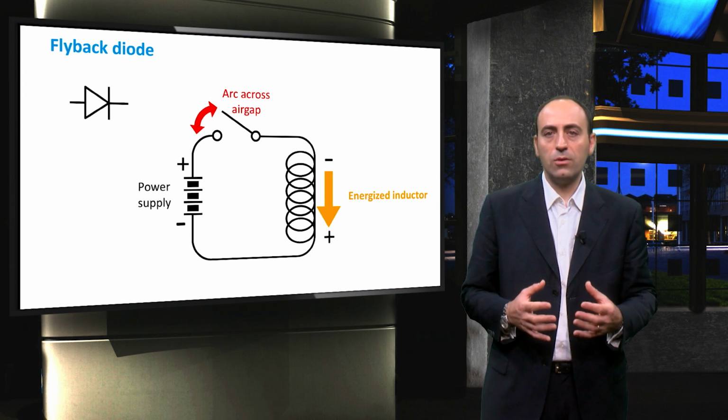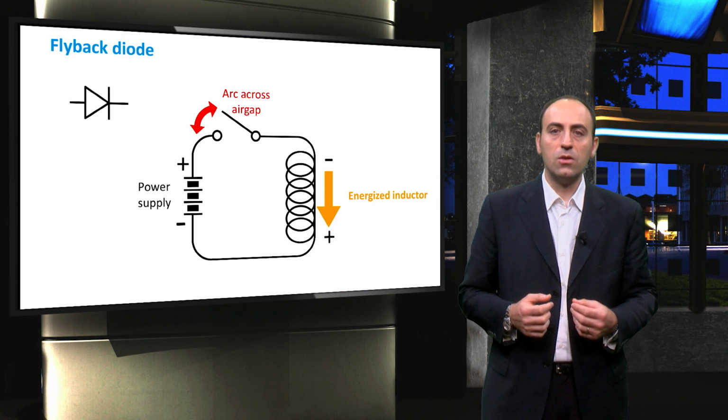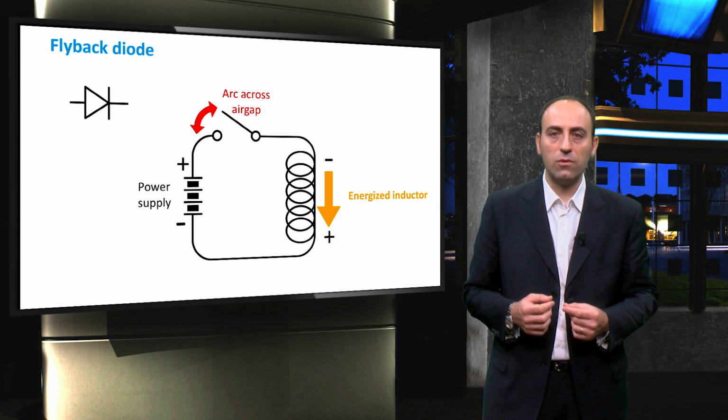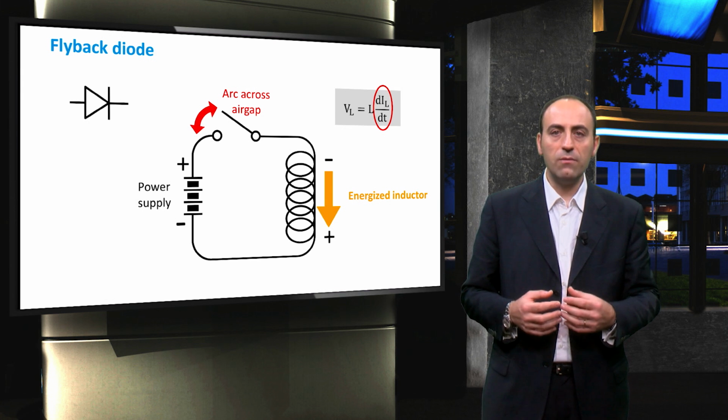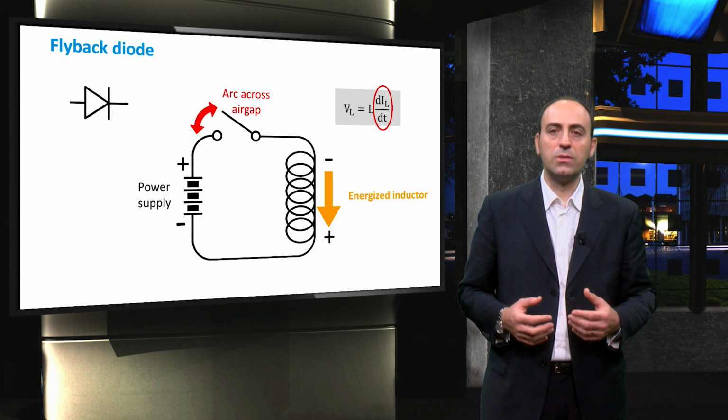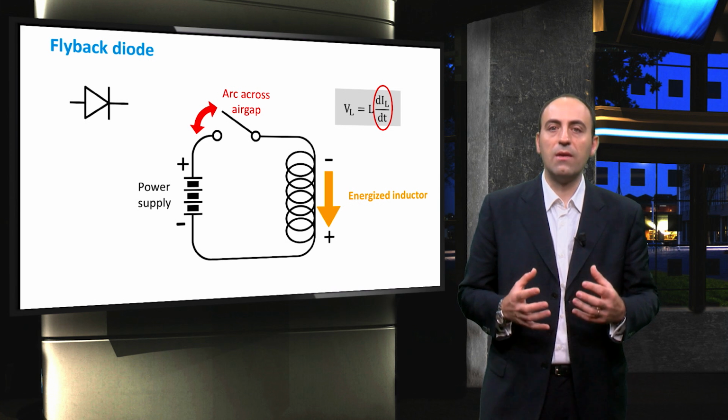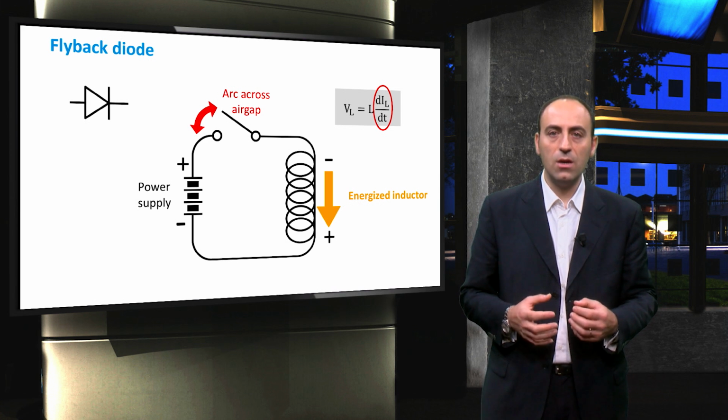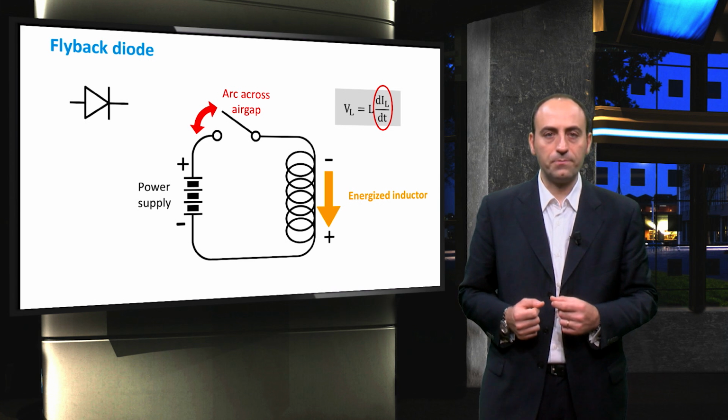Problems might occur when the switch is very fast, so that in a very tiny amount of time the derivative of current becomes very high. This can be potentially dangerous, since if the necessary environmental conditions are met, you could even have a spark.